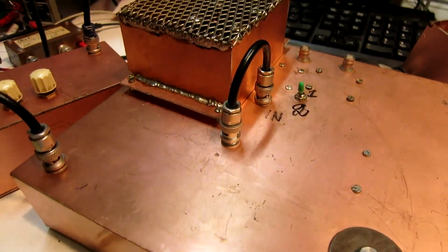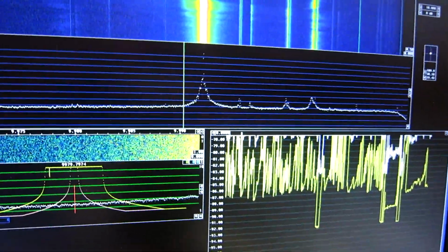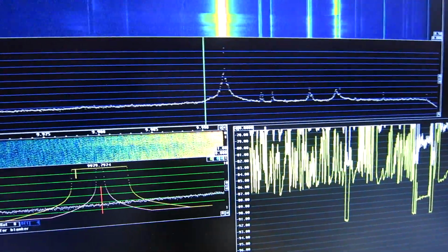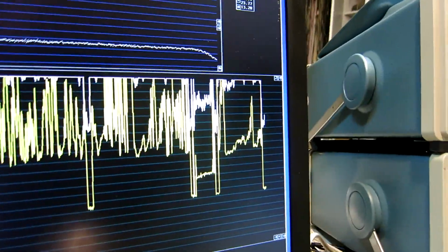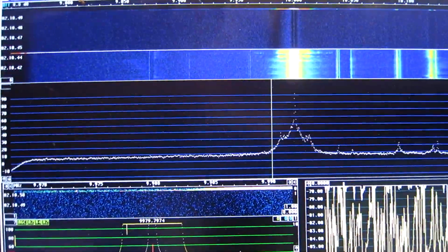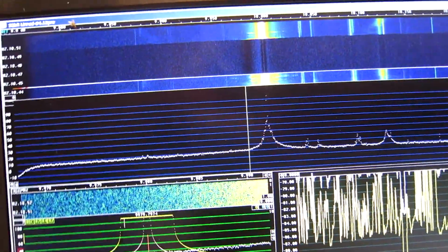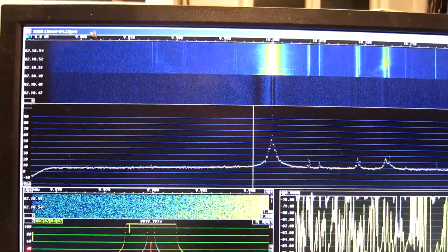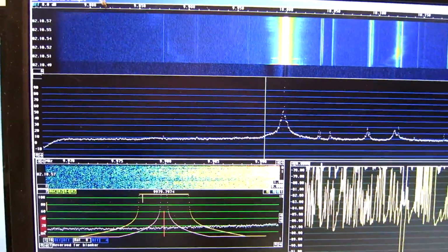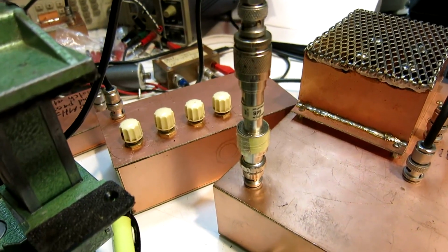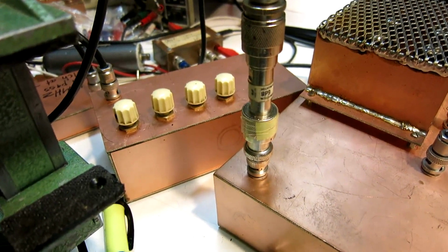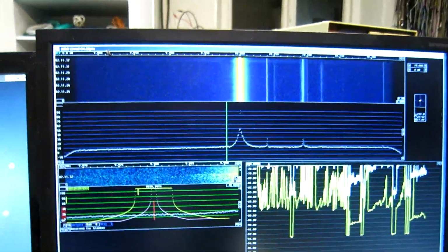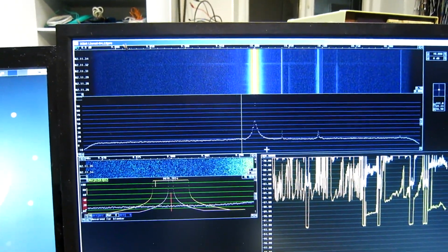Now, running as an oscillator, here I don't see any trace of the notch. Switching off the oscillator, and you can see the noise level is much lower. So this is not the properties of the oscillator, it's the properties of the analyzing system. 6 decibels of attenuation with an unknown addition of noise modulation from the resistors inside. This is what I see. It looks far more stable.